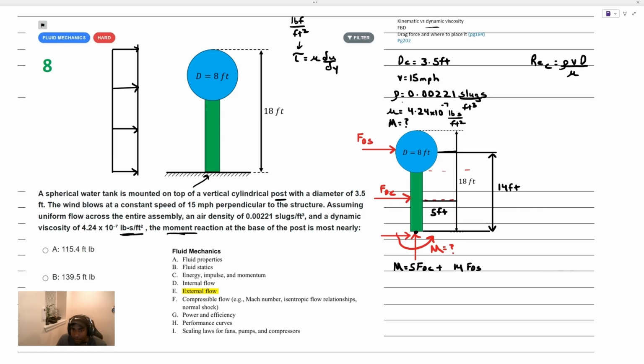I'm going to put foot so we can be more consistent with the units given in this problem. And then the velocity gradient is feet per second divided by feet, so it's just 1/s. If we solve for the units of mu, we end up getting pound force second per foot squared, and that looks very close to the unit we have given in the problem. So I know that that is going to be a pound force there.